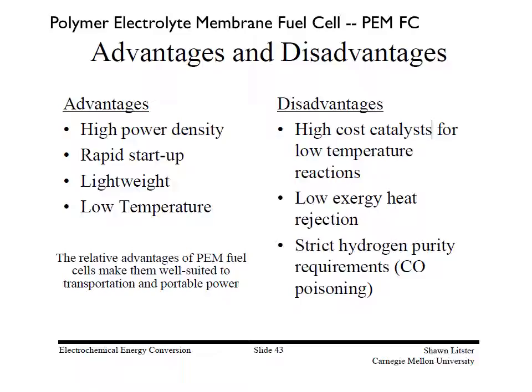This is probably not as big of an issue now that we have membranes that are nearly 100% selective for hydrogen, which means you could have fossil fuels even being reformed on your vehicle itself, as long as it's going through some kind of hydrogen separation membrane before it gets to the fuel cell. And what happens is with carbon monoxide, it sticks to the platinum and basically takes away a site in which you could have a reaction.